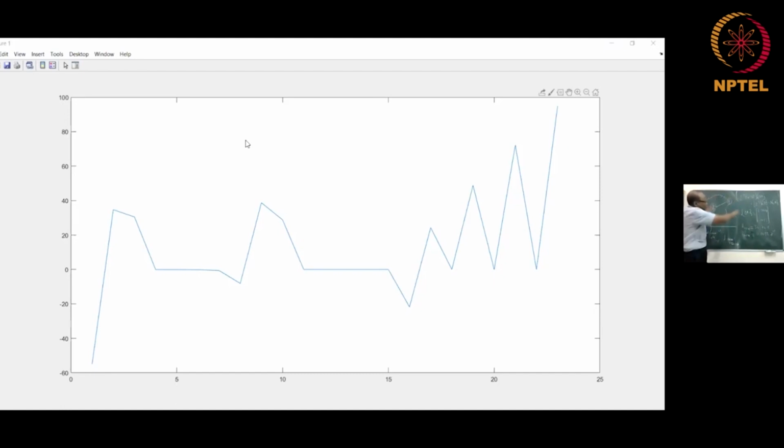So what we can do now is, where is the hope for you? There is a hope. Never lose hope. If you're a practicing engineer, if you're a practicing researcher, what we will do is, I will take A, where A is a temperature excess. I know it is some bucket, dipper, immersion heater, or it's some heat sink. I know that temperature will be 70 or 80 degrees. Therefore, theta has to be 70 minus 30, T minus T infinity is about 40 degrees centigrade.